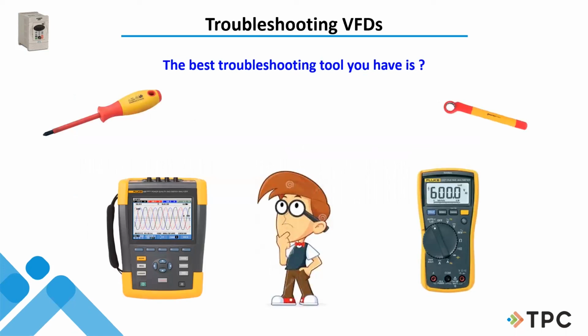The best troubleshooting tool you guys have is the drive manual. If you don't have the manual, it's going to be tough to know what parameters to look at. And so you should have your manuals where your drives are so that anybody can get to it. And having the right meter, that's important, and the right tools, those are all important. But if you don't have that drive manual, you have really handcuffed yourself. You got one hand behind your back.